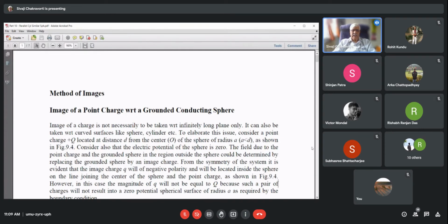So in those cases, please remember this, sphere gap is the perfect switch. Because when the gap is not broken, that means there is no breakdown, this is an open circuit, and natural atmospheric air is the insulation, so you don't have to give any additional insulation. But as soon as the voltage reaches the breakdown voltage, the gap fires and the switch is on.